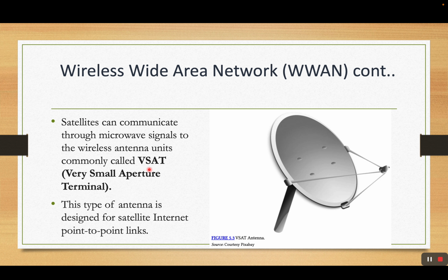Usually, the size of the VSAT antenna can be as small as 75 centimeters in diameter and as large as 3.8 meters in diameter. But in standard satellite ground station communication, the maximum size of the VSAT, especially for internet connectivity, is about 1.2 meters in diameter.